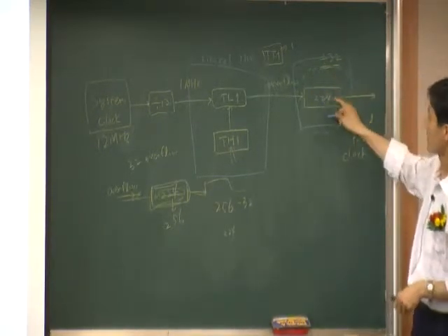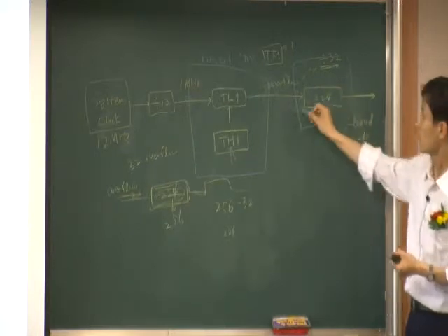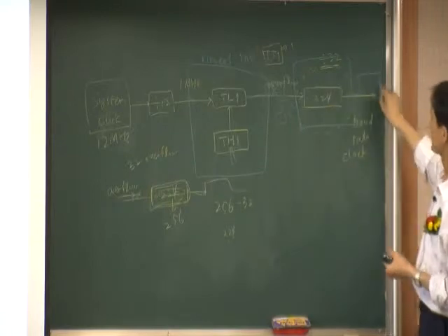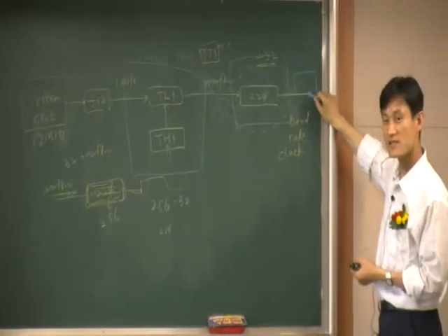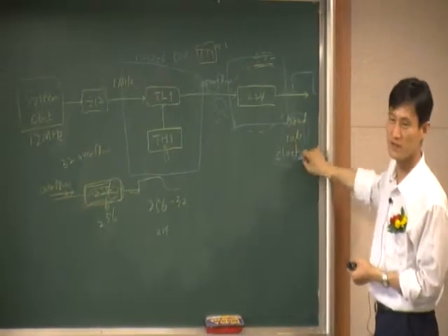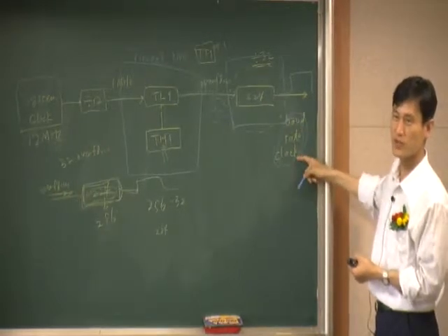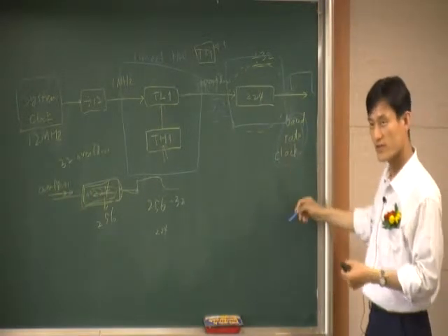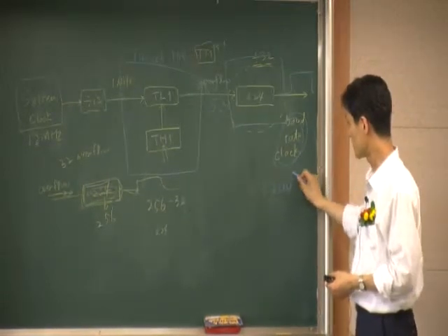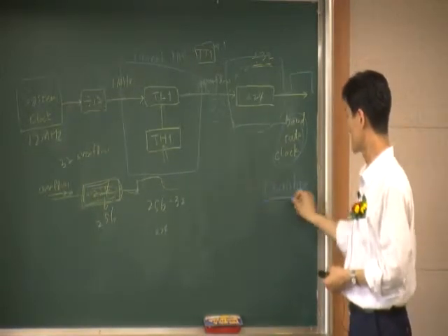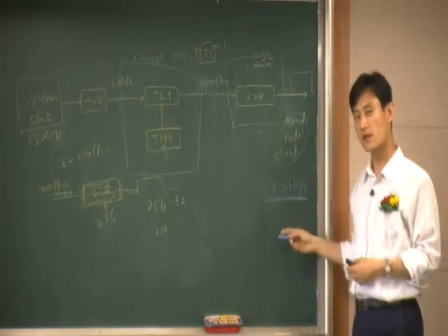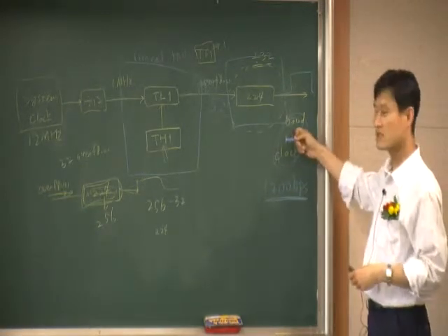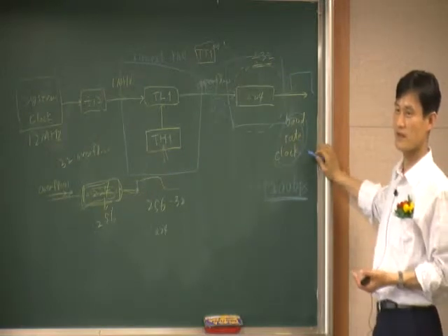Inside this hardware, again, there is a counter. So whenever you have 32 overflows, now you get a 1 output. That's the baud rate that we want. This is the output we want. And how much baud rate do we want? For example, this one, 1200 bps. This is one example. So this is the rate that we want.